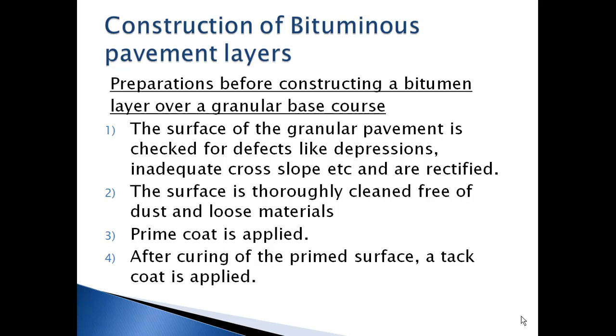After that, the surface is thoroughly cleaned of any free or dust materials on it. On top of that, a prime coat is applied. After curing of this primed surface, a tack coat is applied.